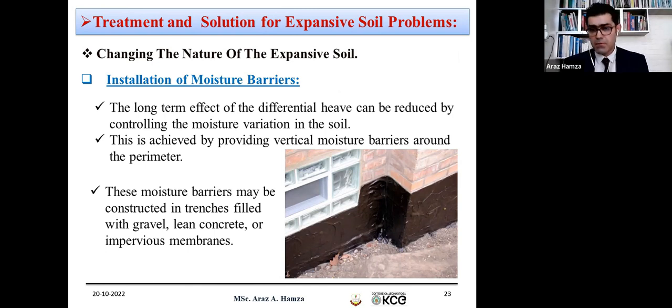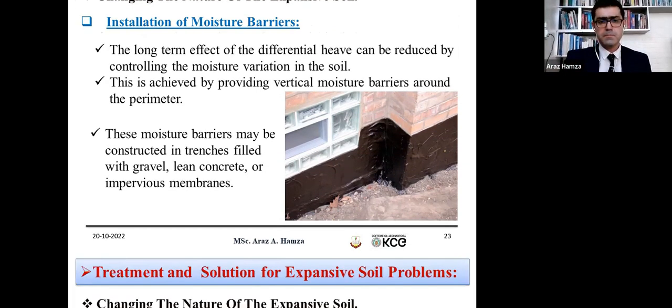This will be a very good technique, and it can also be done with a trench filled with gravel, lean concrete, or impervious barriers, everything by compacting. You can think about how you implement this idea. It is up to you which type of material you use, but the main idea is to isolate your foundation from the outside water.